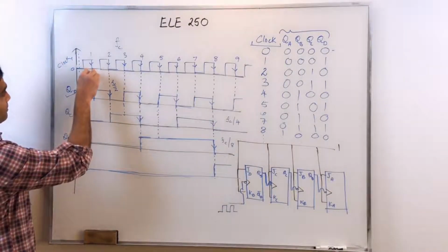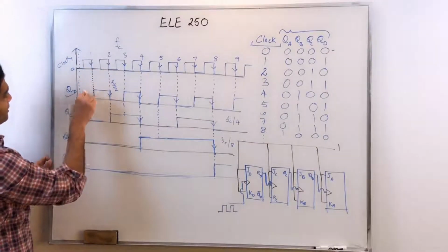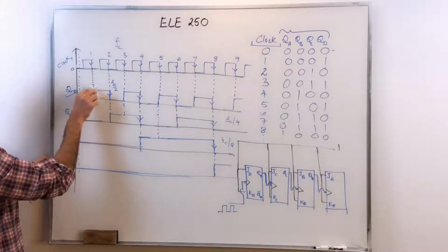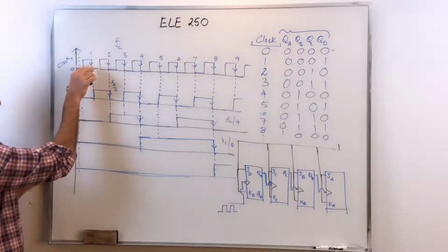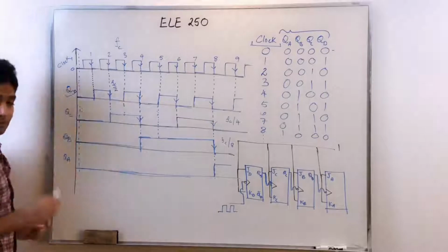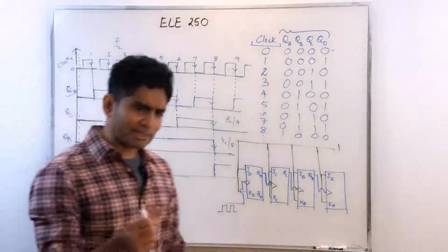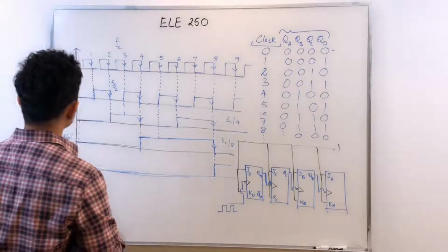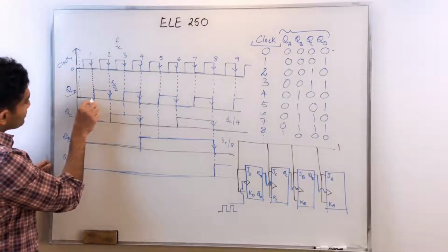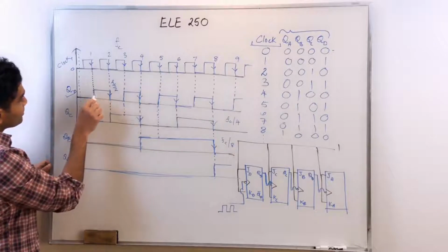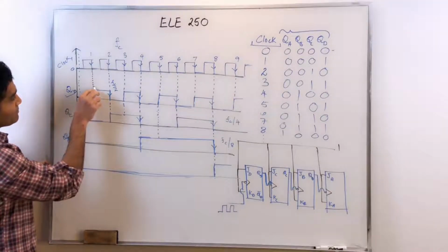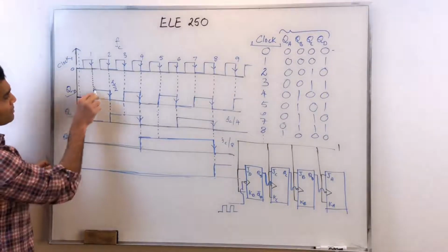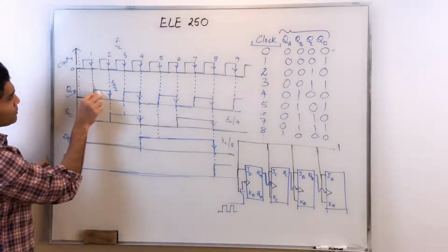Here is an idealized situation where the toggling of QD is exactly matched with the active edge. In reality, because of the slight delay for the conduction of signals through the flip-flop, it is going to switch after a slight timing delay, something like this.